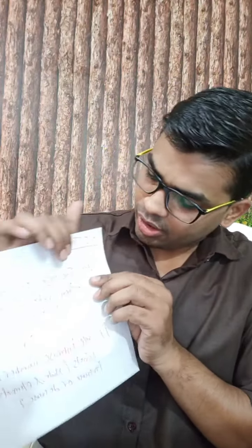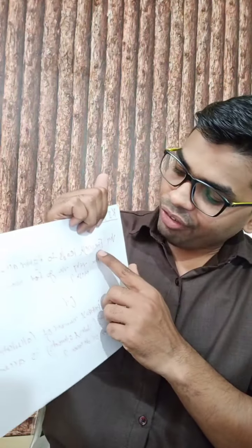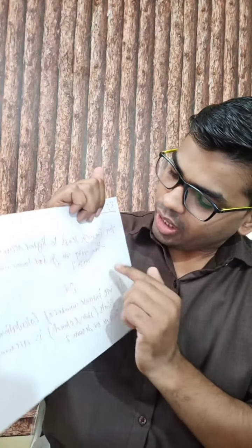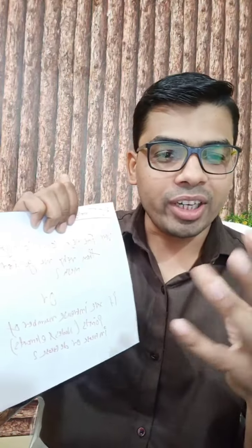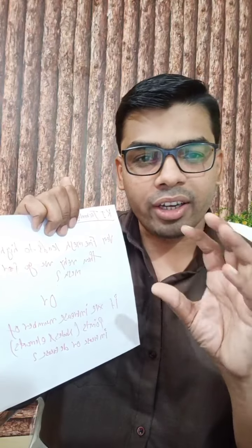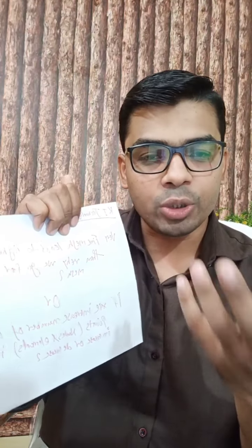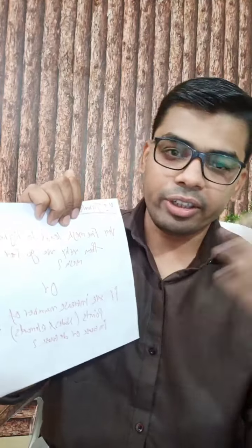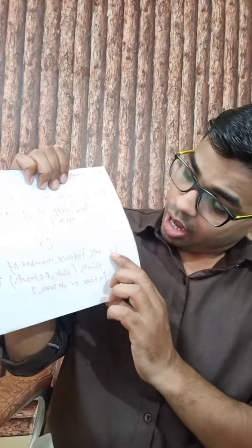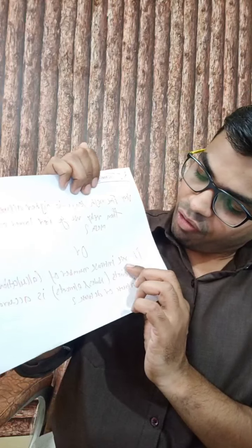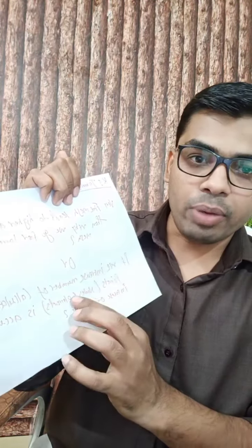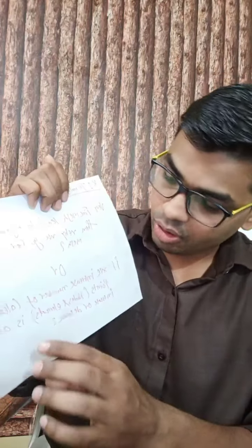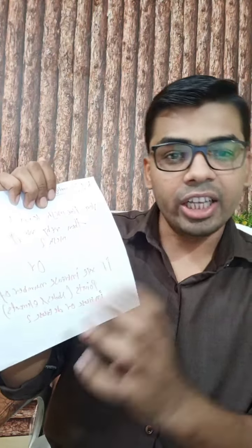And today's question is, I hope it's visible to you guys. Very fine mesh leads to a higher accuracy, then why do we go for a lower order mesh size? I mean, if a fine mesh is better, then why are you going with the coarse mesh? Directly you should jump to the fine mesh. Or in other words, if we increase the number of calculation points, nodes and elements, does the accuracy increase or decrease?